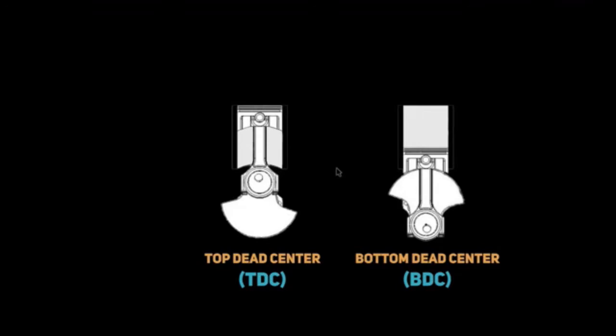Now, the engine provides the energy to propel or move the vehicle and operate the other systems within it. Usually fuel, such as gasoline or diesel, is burned within an engine's combustion chamber, which causes expansion of the gases in the engine. This pressure is then converted into motion to then move the vehicle. So as we see right here, we have the combustion chamber, the piston, the connecting rod, and the crankshaft. So let's get into these specific ideas, the top dead center and the bottom dead center.